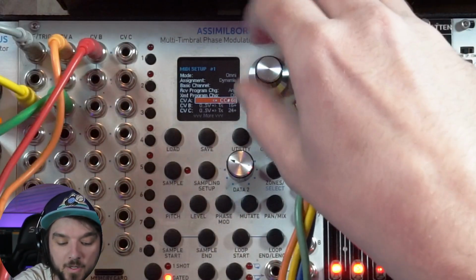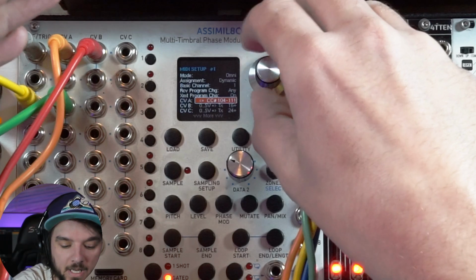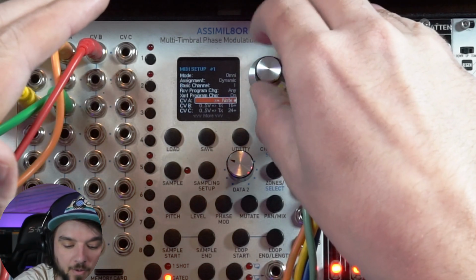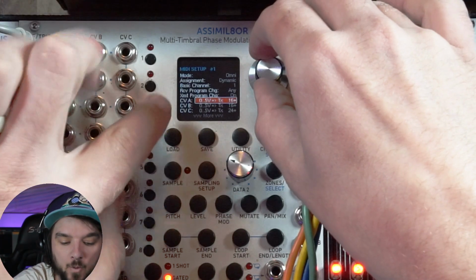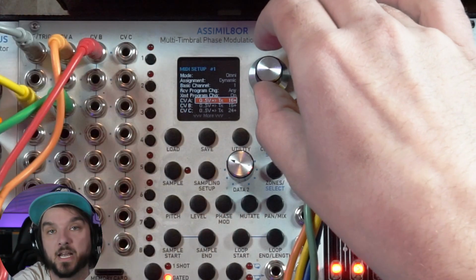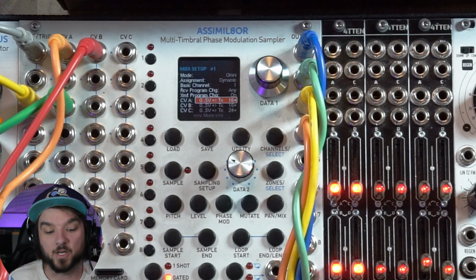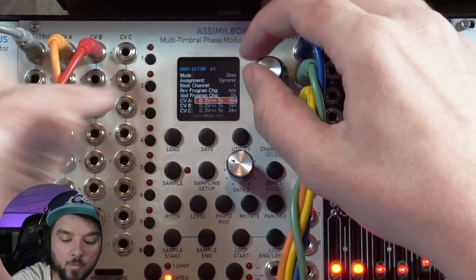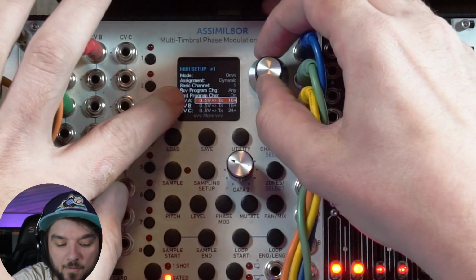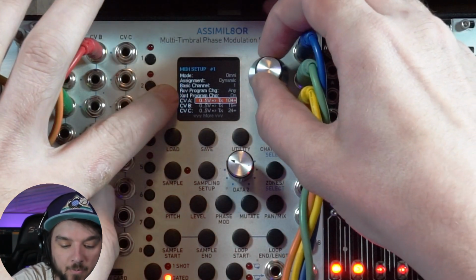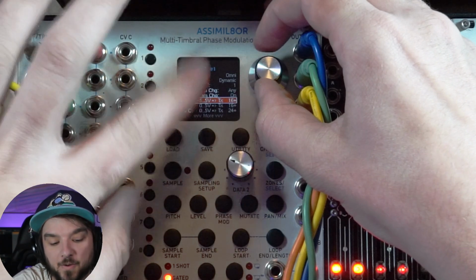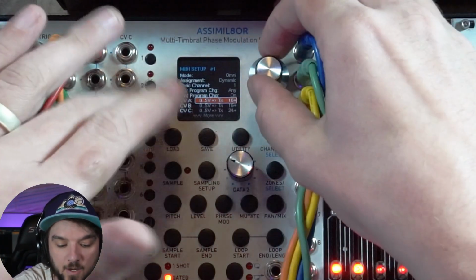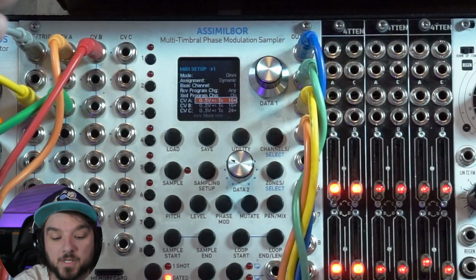But if you go further down the road, we can see the arrow will switch after we get through velocity and things like that. We can go through and the arrow switches now to the right. And this means that it's going to transmit CCs from the CV inputs. And we've got 0 to 5 volt settings. And then we've even got negative 5 volts to 5 volts, so bipolar settings. Because I'm using the 410s, we're just going to stick with the 0 to 5 volt settings.